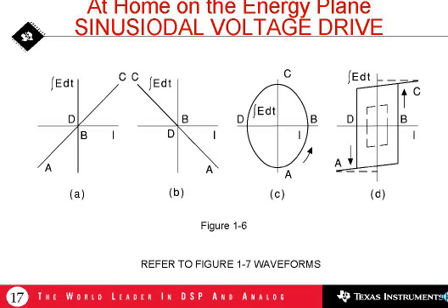Okay, now that does show these metallic materials, even though they tend to be almost ideal, they do have hysteresis. It does take a finite amount of current or magnetic force to change the flux through those devices. Once you reach that critical threshold of magnetic force shown on the current axis at point B, then the flux will change, but it does take time to change the flux, to move up and down in that vertical direction, because we're moving on a volt-second axis.